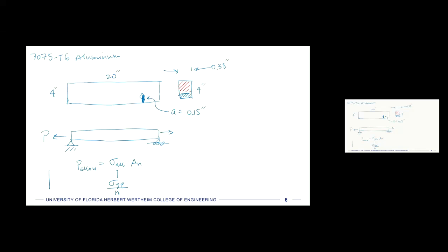So this is our failure criterion for just static yielding. Sometimes in undergraduate classes, we refer to this yield stress as a yield stress in tension. You'll use that when you're talking about threaded fasteners and things, so you can assume that this is the yield point in tension.